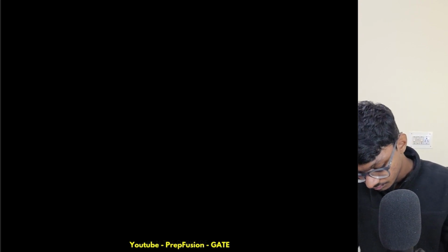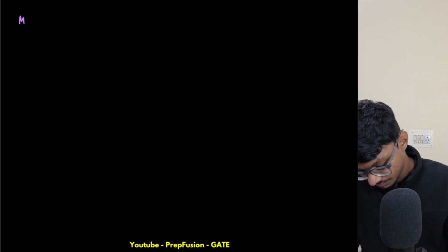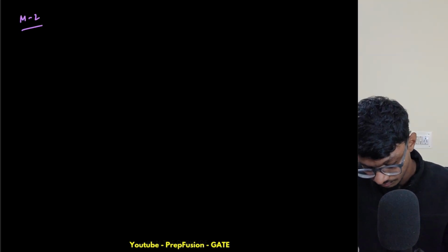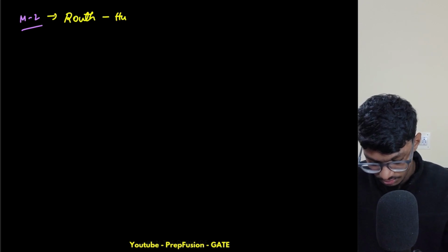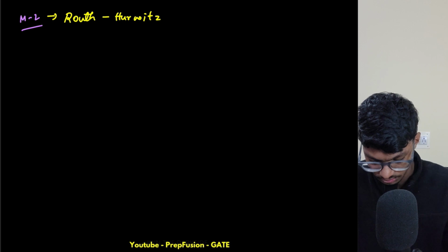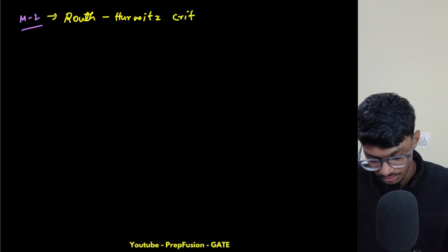Both of them tell us the absolute stability. Sometimes it is easier for us to solve with Nyquist, sometimes it is easier with Routh-Hurwitz. You have to choose which one. You will only understand when to use what method when you solve multiple questions. Method 2: Routh-Hurwitz criteria.